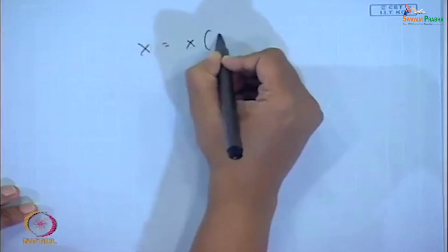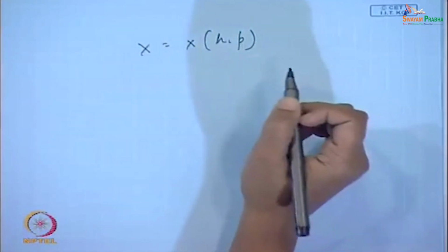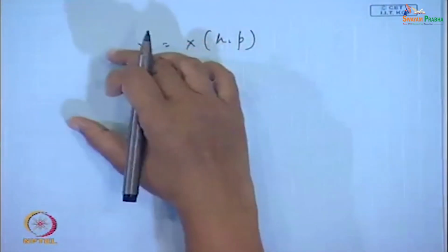So, we will be doing a problem on it, and there you will find that if kinetic energy effects are quite pronounced, then in that case x as a function of enthalpy and pressure does not hold any longer, and for that particular case we have to go for something more elaborate. We have to write the actual energy balance equation with the kinetic energy, potential energy, all the terms. From there we have to find out the proper expression of enthalpy, and that has to be substituted in the pressure drop expression, and it has to be done accordingly.